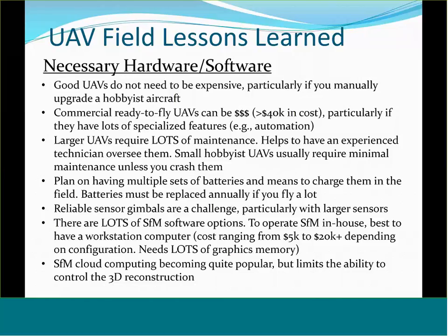I want to point out, it's been our experience that large UAVs tend to require lots of maintenance to keep them running well, and it helps if you have experienced personnel or a technician oversee that. The small platforms, like the little DJI quad rotors, tend to require minimal maintenance, and they're very reliable, but the type of data we can collect from them tends to be limited because they can't carry a very large sensor.